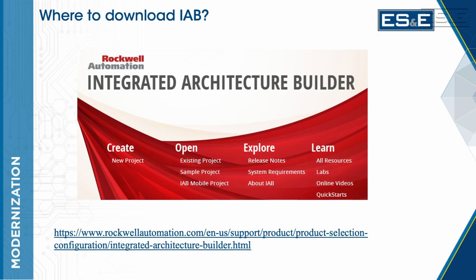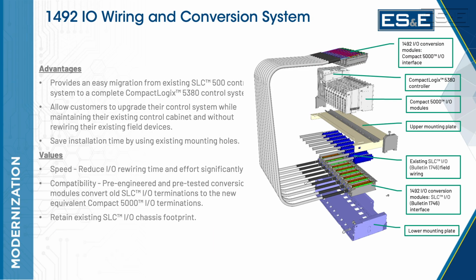In Rockwell world, I'll say this, the software is free. Unlike programming software, right? This is a free service, and it's free software by Rockwell. And it's used to help aid in situations like this. You're going to remove all the Slick I/O cards and everything, but you're still going to use the wiring that's connected to the Slick. Because if you open up the Slick door, there's actually a little terminal block in there, and that whole terminal block can come out, okay?